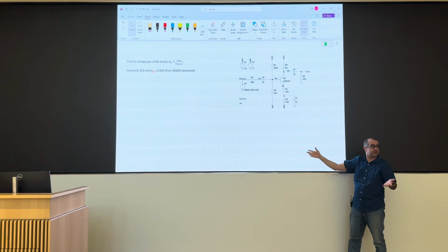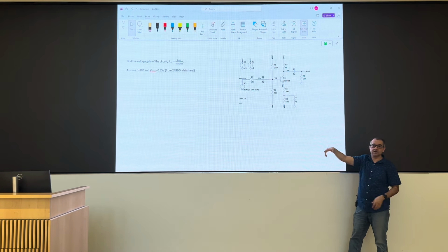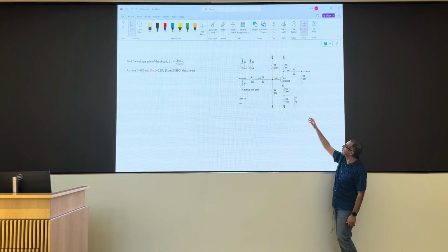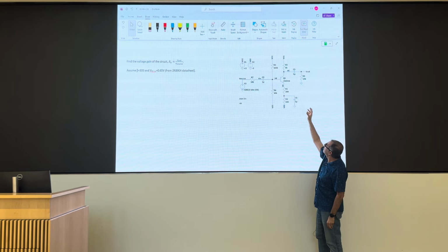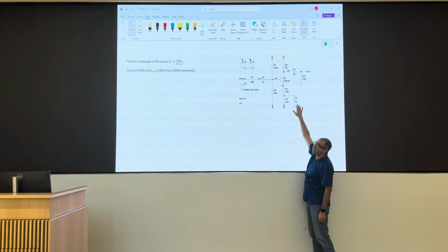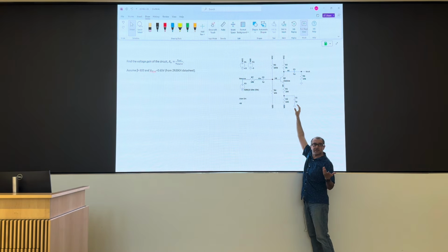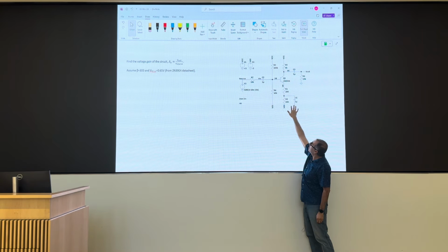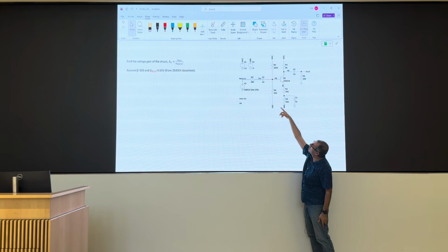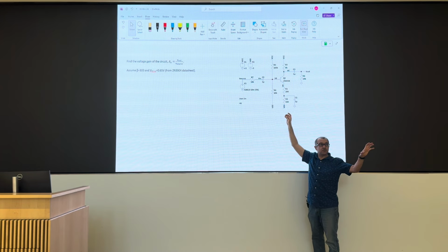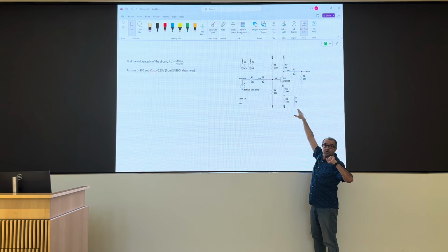It may or may not be a resistor. It could be an oscilloscope probe, right? From what we are considering. And then notice that I'm using relatively large capacitors, 1 microfarad, to bypass this resistor or couple the source to my input or the load to the output.